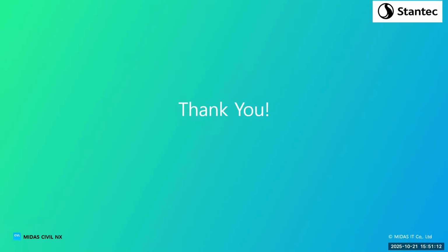Sounds good to me. A follow-up question: is it difficult to find time history records with similar site-to-source distances and similar ground properties? Not really. I know Europe has a database, I think it's ESM. They've got quite a good database. That's actually another criterion you can use, the epicentral depth.